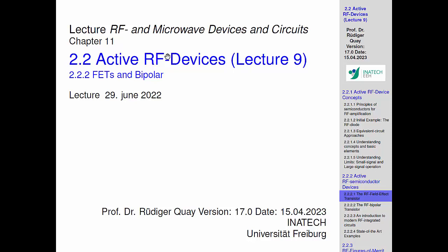And what I would like to explain next time is that the bipolar is particularly advantageous because it can realize current amplification on a small area. Now you could say, why am I interested in that? The reason is the difference between a tablet and a cell phone. If you would build a cell phone with FETs, it would have the size of a tablet. That's why we use bipolars, because you want to be able to put your cell phone in your pocket.